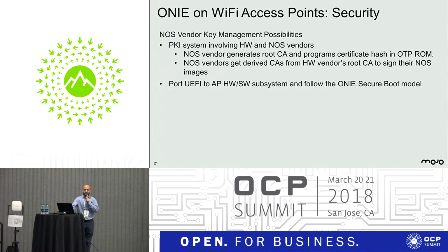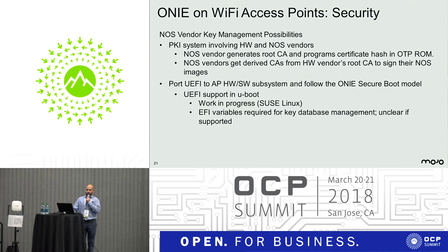The other way of doing it is that we can port UEFI to this AP hardware software ecosystem, and then we can follow the same ONIE Secure Boot model that is being proposed for the switching world. So UEFI in U-Boot is a work in progress by the SUSE Linux group. In fact, they presented recently at an embedded conference.